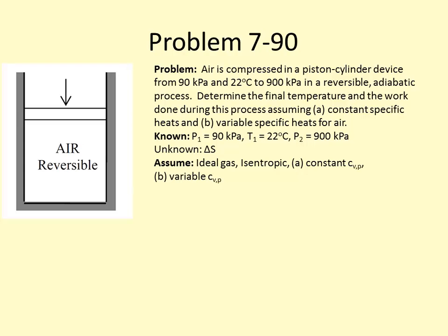So then we go back to the table and we say, okay, at what point do we have a pressure ratio or reduced pressure equal to 13.068? So we look on here, it's somewhere between 560 and 570 Kelvin in the temperature.